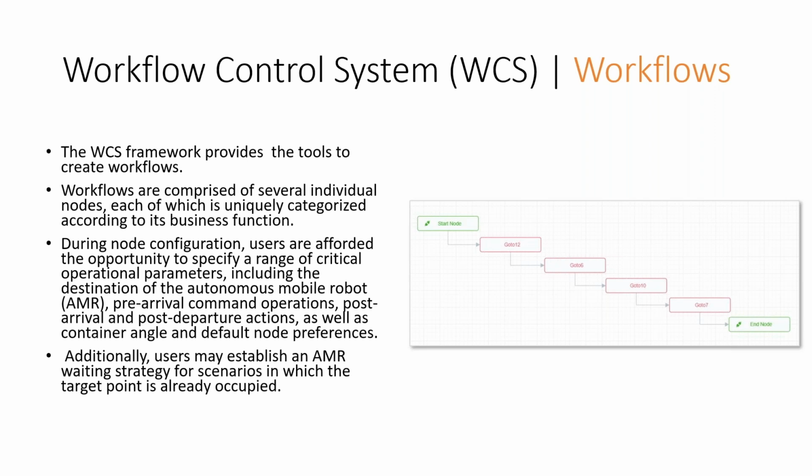You can specify the angle that you want your container to travel between on the edges between the locations, and you can create waiting scenarios where you can dictate an area of the map that could be a queuing location when you're waiting for availability to go, for instance, pick up containers and move them to another part.